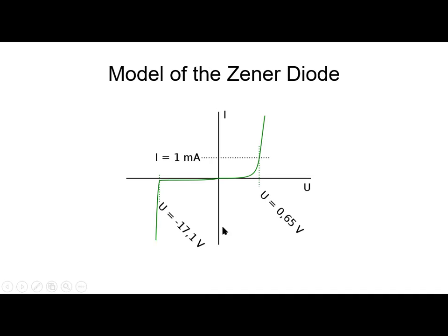How do we represent the Zener diode for computations? Let's look at the behavioral curve of the Zener diode. Here on the front, the Zener is just a regular rectifying diode that when the current is between a certain value and another one, the drop in it is approximately 0.7 volts. We will not use the Zener there. We are interested in the Zener working in the breakdown zone that we are calling now the Zener zone. In that zone, you see that the line is almost vertical.